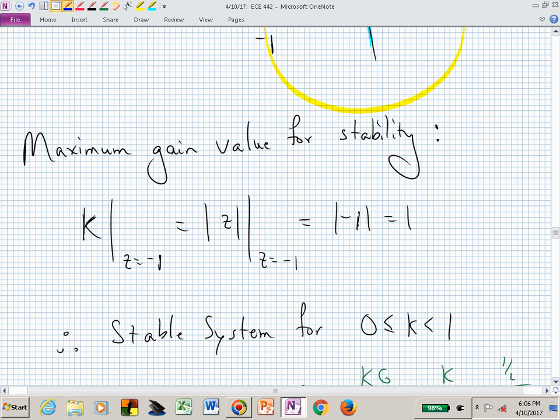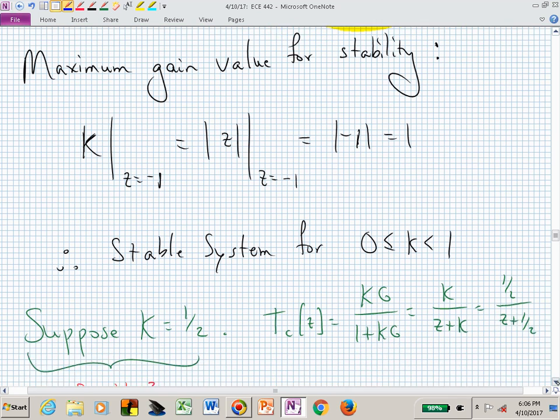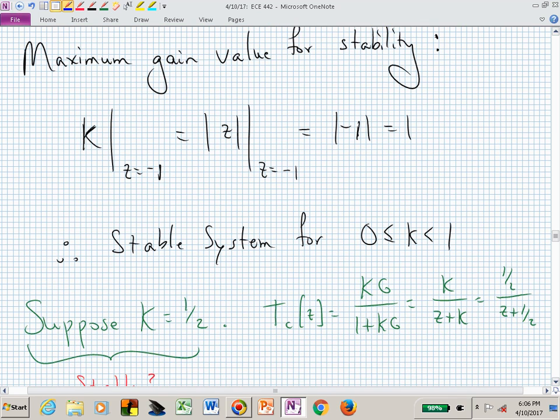That's why that's the case. Well, you'll find that if you plug in a pole value into the expression for k, that's always going to evaluate to 0 for your gain. If you plug in an open loop pole value, because all of those factors are in the numerator of the k expression, you'll get k equal to 0 at your open loop poles.